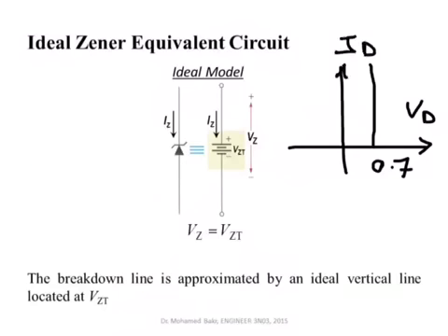But when you apply the breakdown region, the current will be effectively 0 until we reach a certain value, and then it breaks down, and this can be maybe 5 volts. It breaks down at 5 volts. This voltage here is minus 5 volts, but we rarely mention the negative here. We say that this Zener has a breakdown voltage of 5 volts, meaning that if you make the cathode more positive than the anode by 5 volts, then you enter the breakdown region.